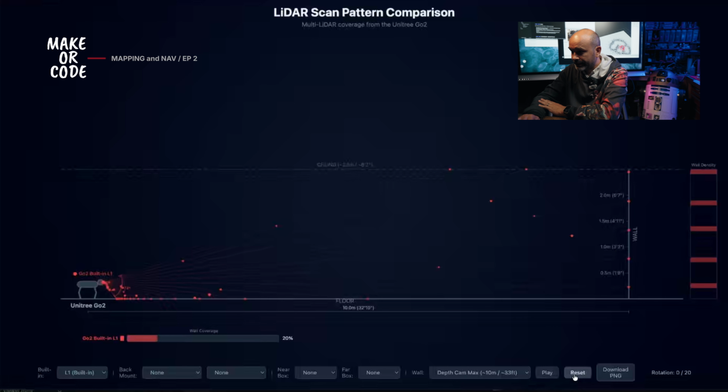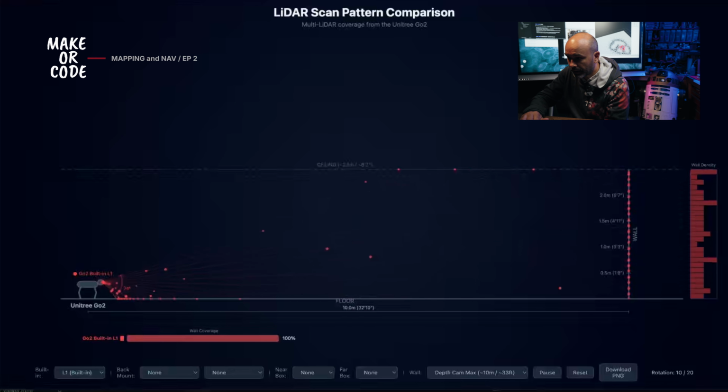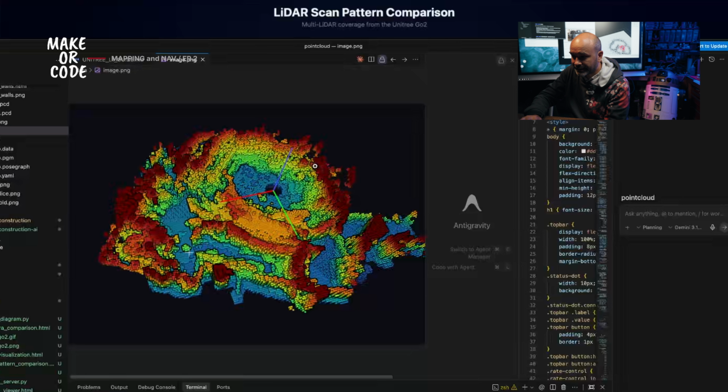So again, if I reset this, the first pass will only see the wall with a couple points. And then I walk and I'm now looking somewhere else. The amount of points that I've actually hit the wall is very small. It's not a large amount. If I were to walk, stop, wait, walk, stop, wait, and continuously do that, then I will start to get a better picture of the wall. When I look at this plot, in some places the red is very dense, and in other places it's not as dense. It's just because I swept through and walked, but I never slowly, step by step, walked in a more constructive way to start building out the entire wall.